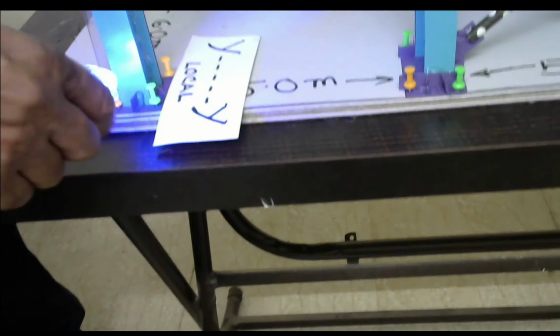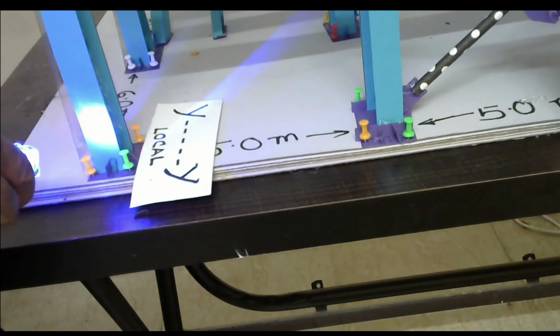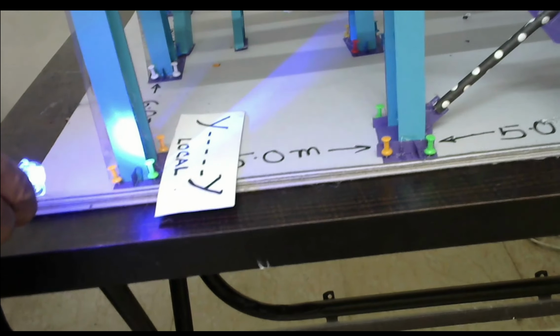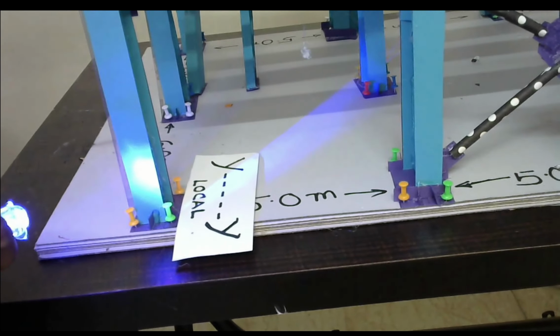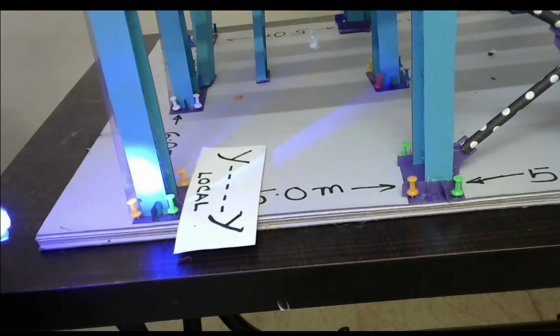So only these two plates will have some inertia. So obviously this will have some movement capacity, but for design consideration, we usually consider either a big joint as fully fixed or fully pinned or fully released.